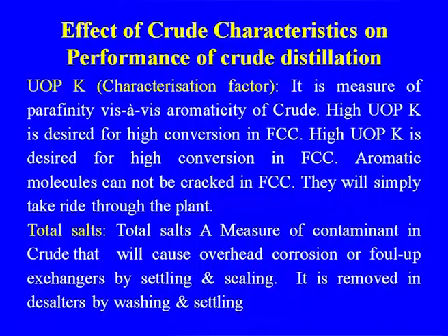Characterization factor, already we discussed, is a measure of the paraffinity of the crude. High UOPK is desired for high conversion in the FCC, and aromatic molecules cannot be cracked in FCC. So, depending upon the characterization factor, you can have an idea of the products which you are getting from the separation.